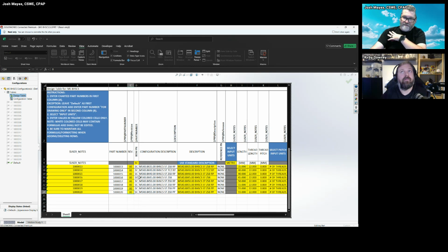And then the part number, how it displays in the BOM, this $PARTNUMBER property, $C tells it to use the configuration name. So not only am I writing out the part number, but I'm also telling the BOM to use the configuration name. So no matter if I'm looking at a data card variable in my PDM system, or driving my title block, or whatever the case might be, I'm going to get the same answer because these two values are the same.